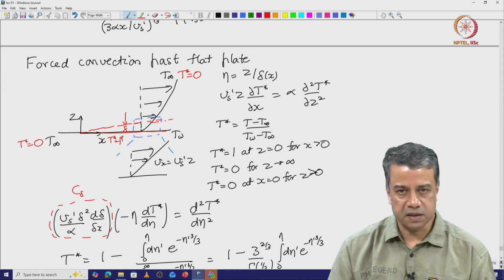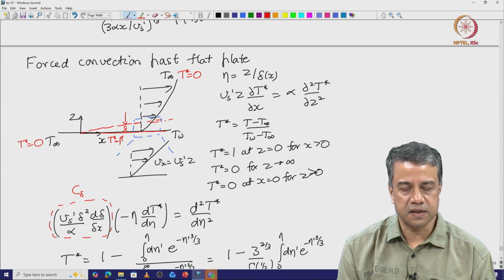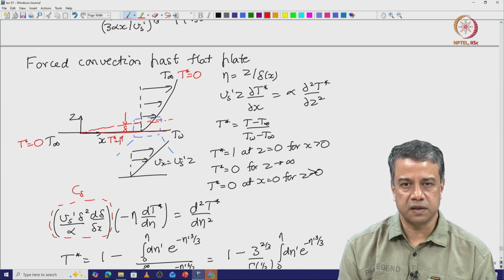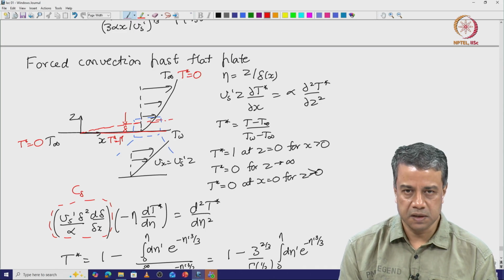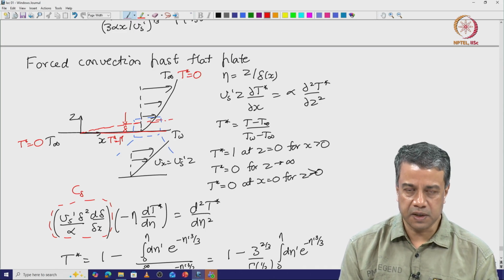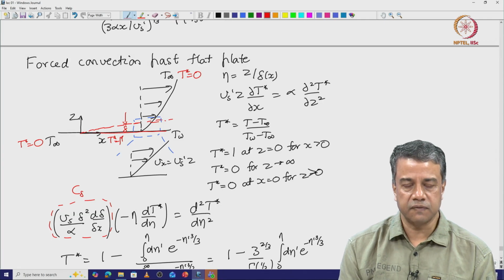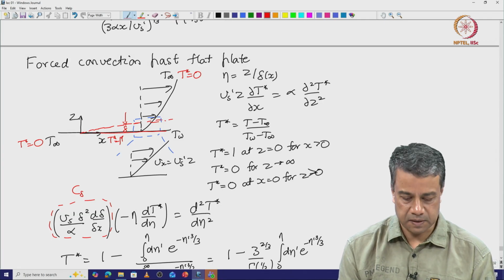In the limit as the Peclet number, the ratio of convection and diffusion, becomes large, the parameter delta becomes smaller and smaller in such a way that convection and diffusion are comparable within this layer.